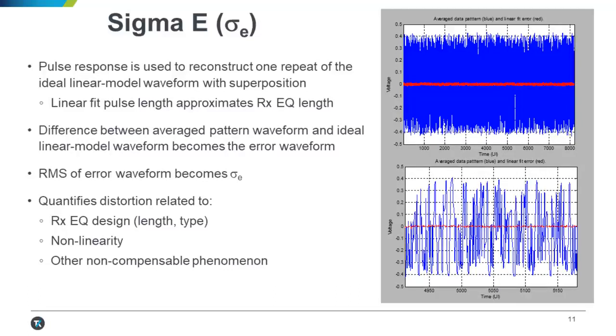We've taken a slightly different approach for PCIe, whereby we're allowing that tail to be extremely long. So we're really looking more at what is the best possible SNDR given the signal, and not factoring in that limitation of the RX equalizer, specifically DFE in the same way.